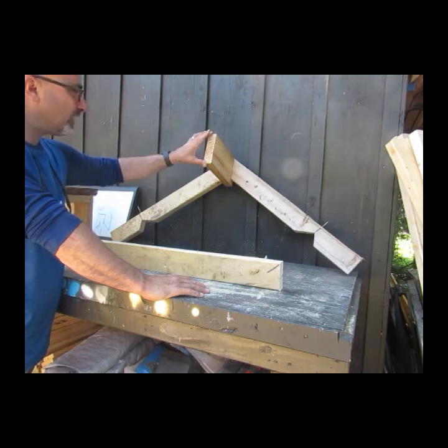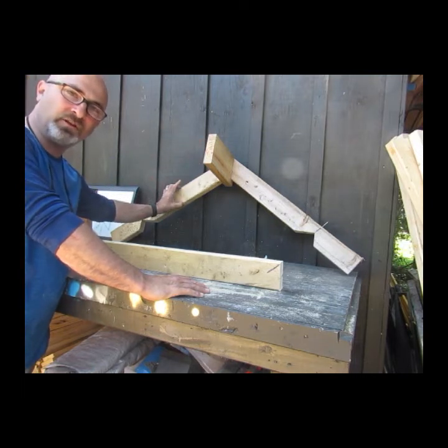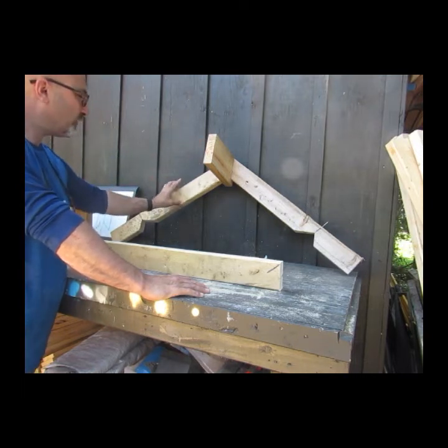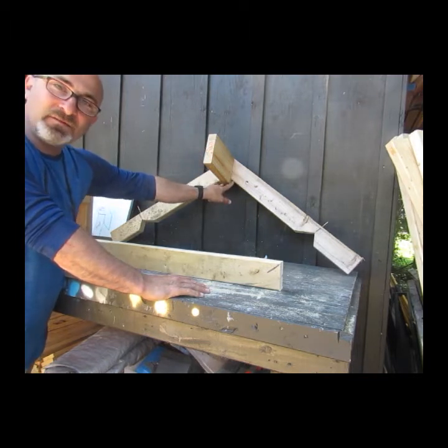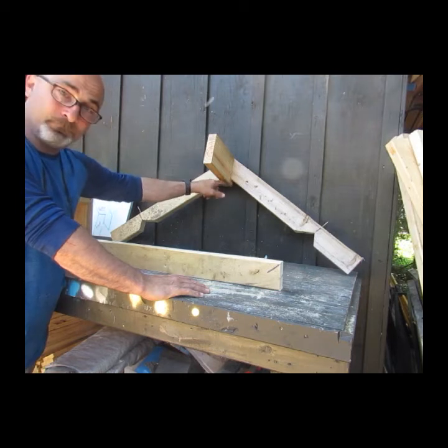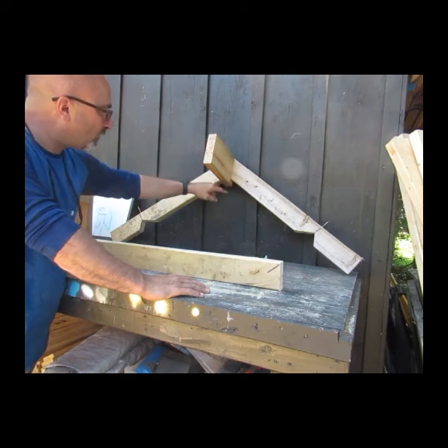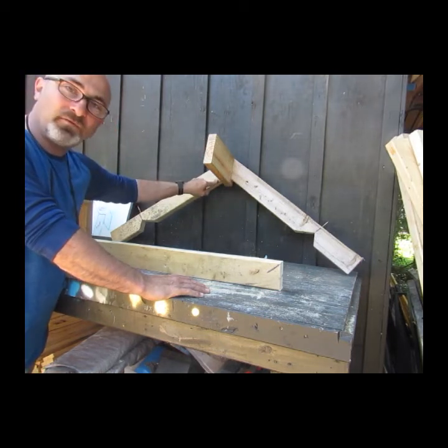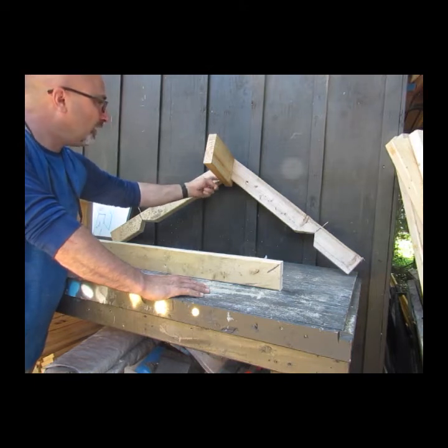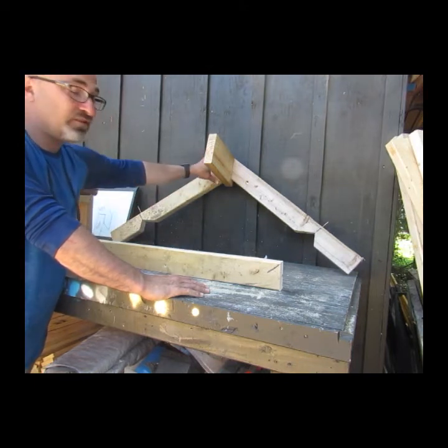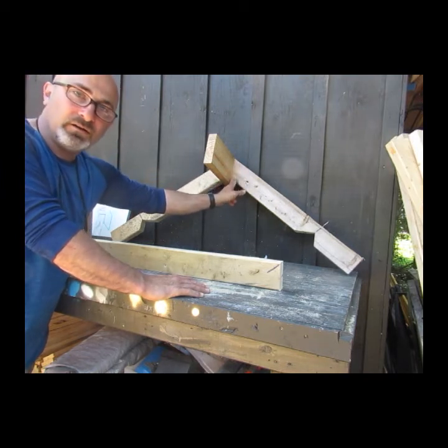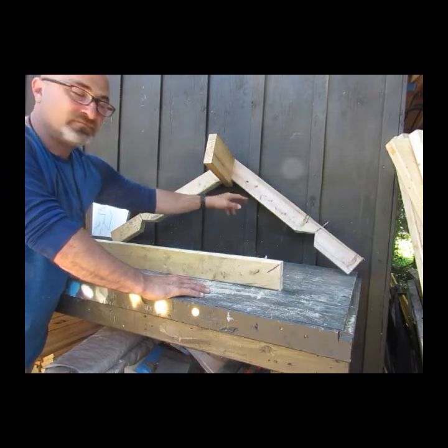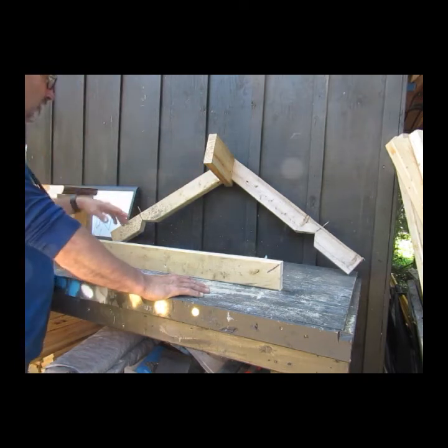So we've got our 2x6 rafters, and the ridge beam is nominally one size of lumber larger. If this was a 2x6, this would have to be a 2x8. As you can see, it's because the rafter needs to be fully supported on the bottom of that ridge beam. If this was a 2x4, the 2x4 would come to here, and the bottom of the rafter would have no structural support. That's why it's got to be that much bigger. Because of the angle, it's a longer surface of the wood than 3.5 inches, so one size up is just fine.